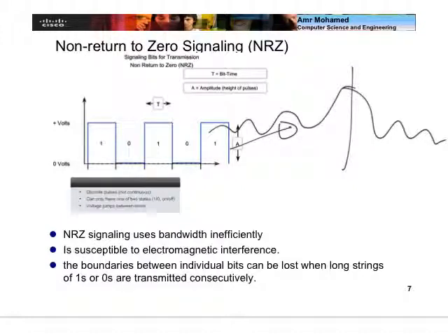So this spans a very large frequency spectrum, which means that it takes a significant amount of bandwidth to be represented in the frequency domain. So even though you are representing one bit using one continuous signal like this, in terms of frequency response, it takes a lot of bandwidth. So that's why this encoding or signaling scheme uses the bandwidth inefficiently, because the bandwidth spectrum tends to be quite large.